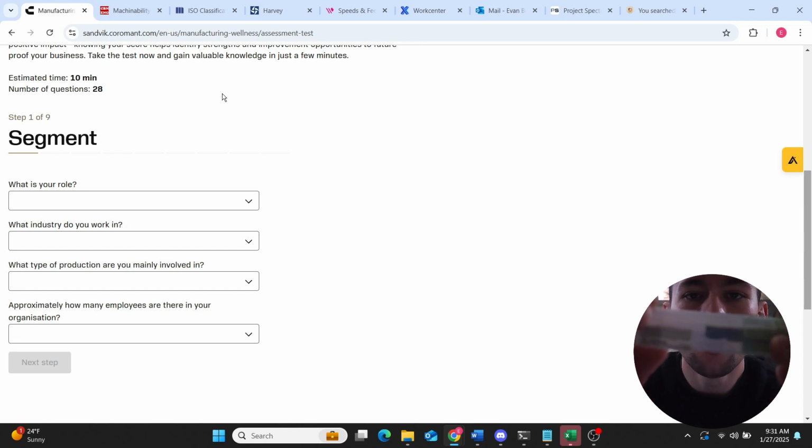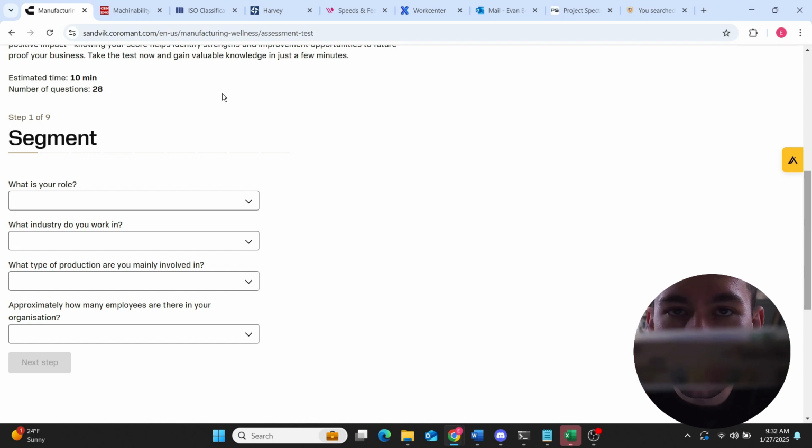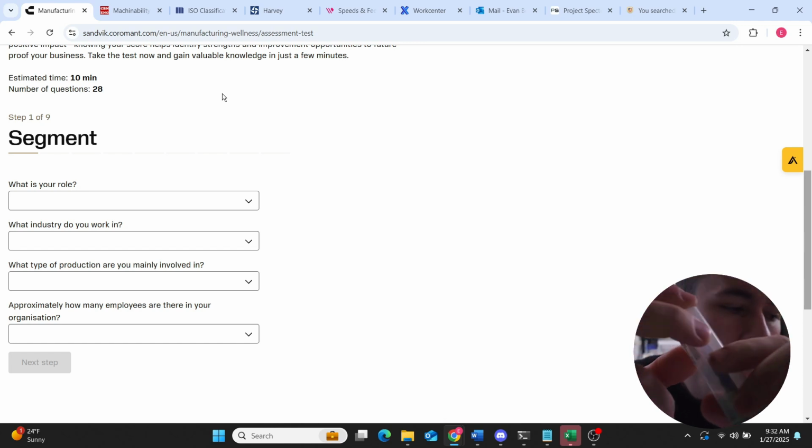So off of this chart here, we can say that it is good in carbon steel, stainless steel, cast iron, non-ferrous materials, and superalloys. The 2 dots in the blue means it's exceptionally good at machining carbon steels.